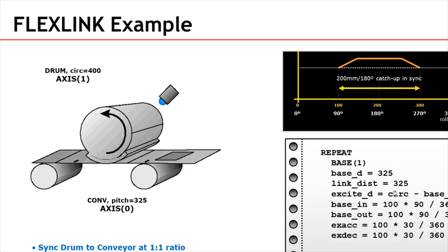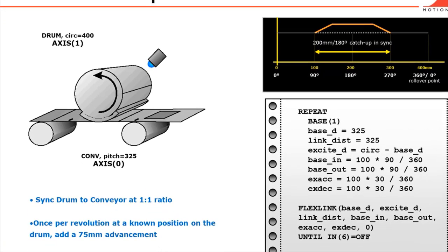So that gives us our 75. Those three parameters really describe exactly the motion distances we're going to deal with. And then the other bits, the base in, base out, excitation, etc., those are percentages. So I said the command itself does a lot of the maths. You just give it the percentage of base in you want and the percentage of excitation, acceleration you want.